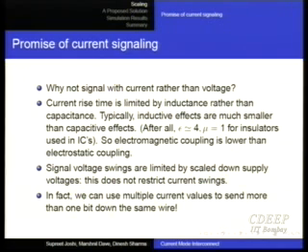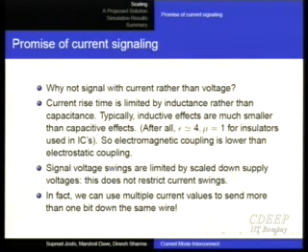Okay? So you have a small amount of voltage, and if you can have appropriately sized transistors, then even in scaled down technologies, in fact in scaled down technologies it is easy because mu Cox is much higher. So therefore you can send larger amounts of current, and because you have a total amount of current which can be quite large, you can subdivide it into 4 fractions and happily have different levels which can be easily distinguished one from the other even in the presence of noise, and send multiple bits. Okay? So suddenly we have found an advantage which we did not have earlier in voltage mode. There will be many such advantages.